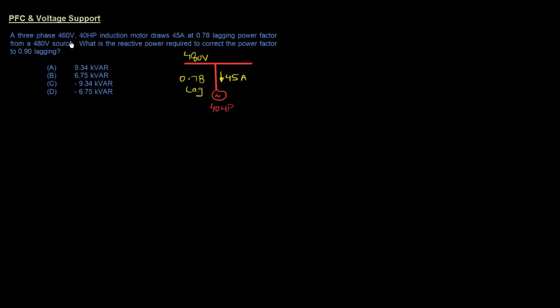This is a NEMA standard that for any 480 volt system, the motor manufacturers state that they can operate the motor at 460 volts. This is just to account for any voltage drop that might be there in the system. But one thing you have to be careful about if you're doing any calculations is that you should use 480 volts, because that's the system voltage, and that's what we'll be using as well. I'll point that out once again when we get into the solution of the problem.